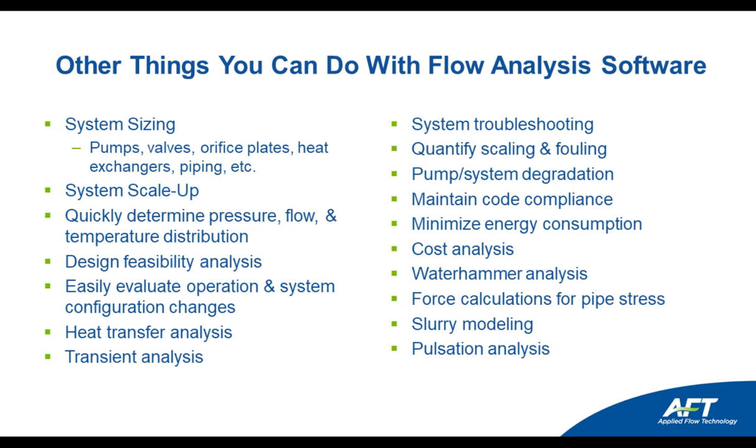And so a good flow analysis software tool would have an ability to figure out essentially how much scaling and fouling might be built up inside your system in order to calibrate your model. Other things that you'd want to capture is your pump and system degradation. If you're modeling corrosive fluids or non-Newtonian fluids or settling slurries, that can degrade your pump performance.